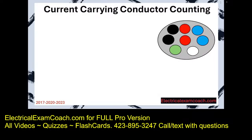Now let's learn about current carrying conductor counting, because we're only going to be counting the current carrying conductors. You may get a question on your exam that gives you the number of conductors. That's easy. You're going to go to the tables and do the math. But you may get a question on your exam that asks you in a scenario of wires, how many of them are current carrying conductors? The first one's easy. All ungrounded conductors. All of the hots are going to be considered current carrying conductors under normal circumstances.